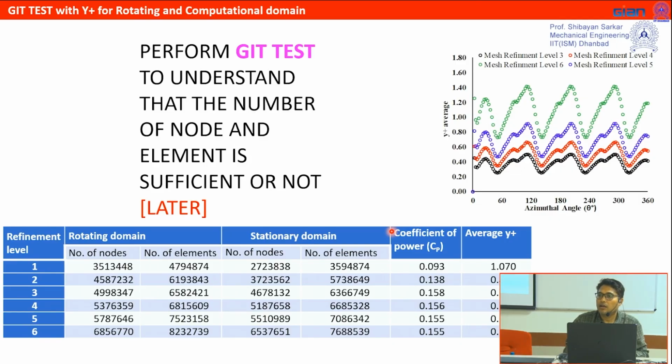So that is the available power, or theoretical power, which is present in the channel. V is the channel fluid flow velocity. A is the cross-section area, the rectangle we have prepared. And then V cube, rho is the density: rho A V cube. This A will be the area of the rotor, rho is the density, and V is the velocity. So that will be the theoretical power available in the channel.